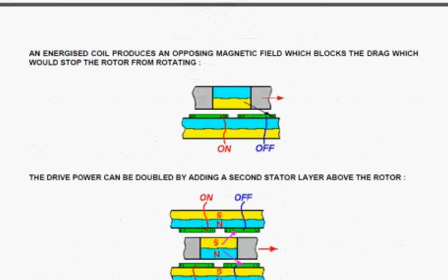Now, what you do is the magnet on the rotor wouldn't move at all if there's no power to the coils, because there'd be an equal pull to the right and to the left, so it would just stay stationary. But if you power, say, the magnet on the coil on the left, it becomes a magnet, and you make the coil and the current which is marked in blue there. That switches off the attraction, and the rotor moves off then strongly to the right.